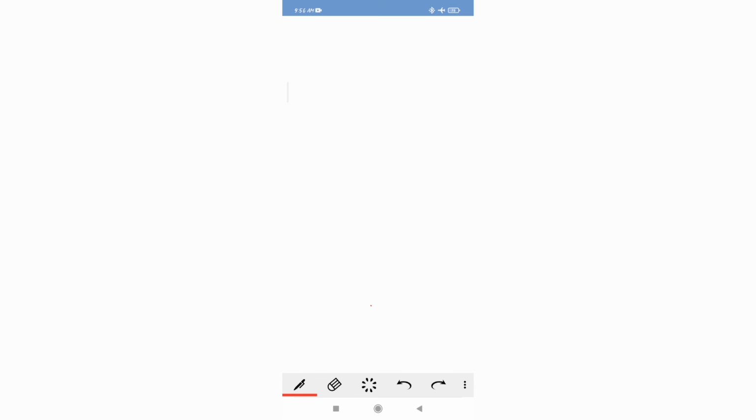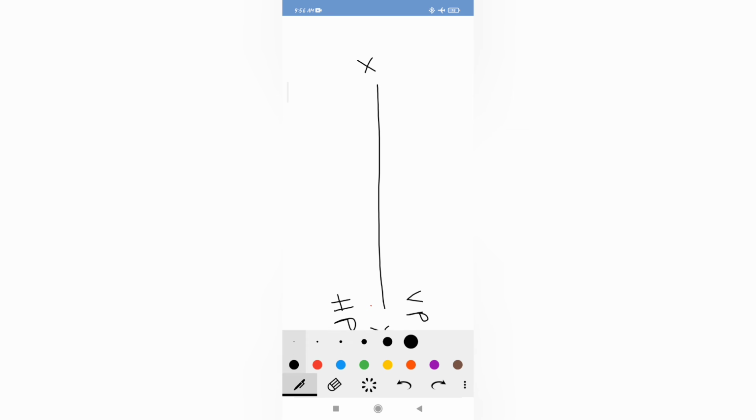Whenever a line inclined to one plane and parallel to the other plane is given, we have to start with the fake view, assuming the line parallel to both the planes. In first angle projection, we know that VP and HP come above and below the reference line, and here 30 mm above and 20 mm in front is given in the question. Therefore, at a height